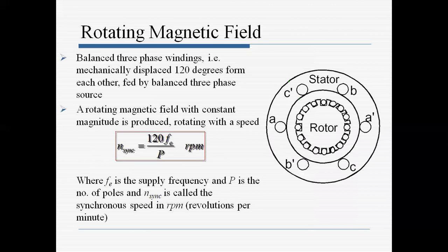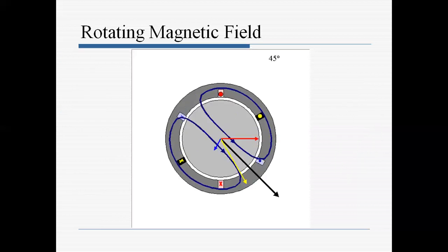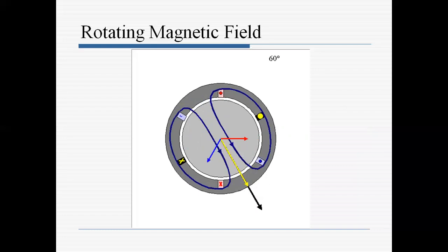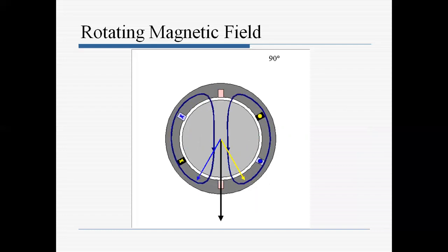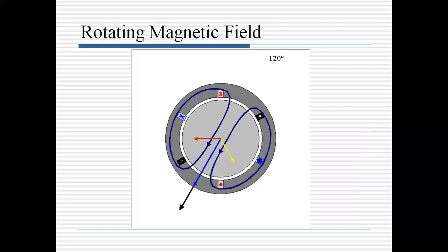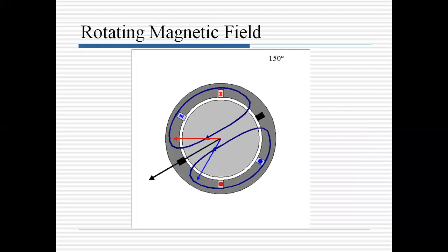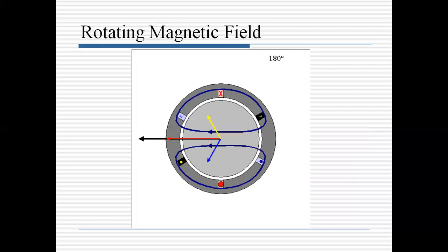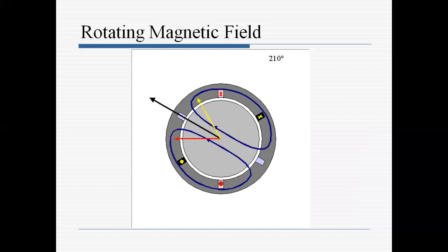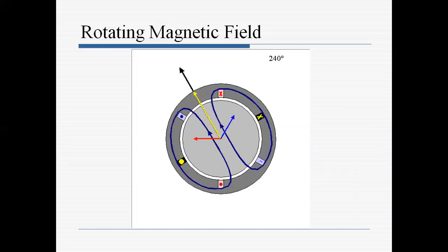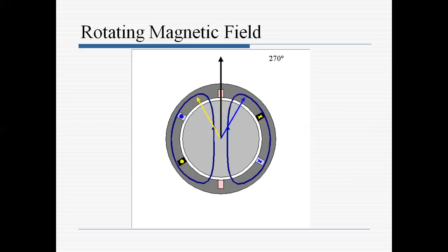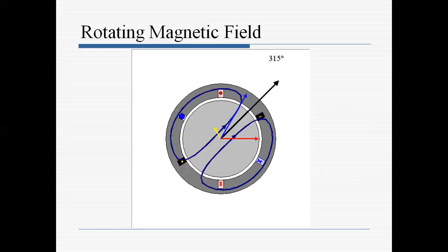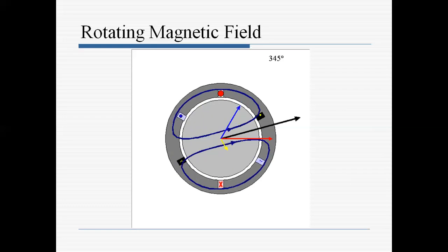in the rotor conductors. Already I told you our field is of rotating nature. We can see from this diagram that our field is rotating, and it is rotating in the clockwise direction with constant magnitude. And one more important point is that our resultant field is rotating at the synchronous speed, corresponding to 50 Hz. Why?